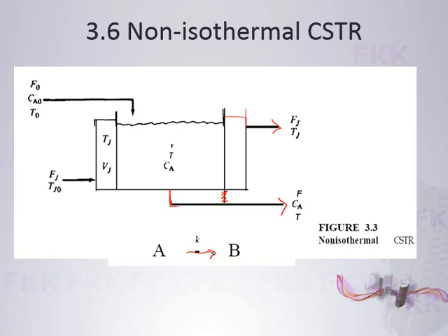In the reactors studied so far, we have shown the effects of variable holdup, variable densities, and higher order kinetics on the total and component quantity equations. Energy equations were not needed because we assumed isothermal operation. So we only need the dynamics of the temperature when you want to measure the dynamic part. If it is isothermal, then you don't have any problem, because the temperature in equals the temperature out, which equals the temperature in the system. So let us now consider a system in which temperature can change with time.